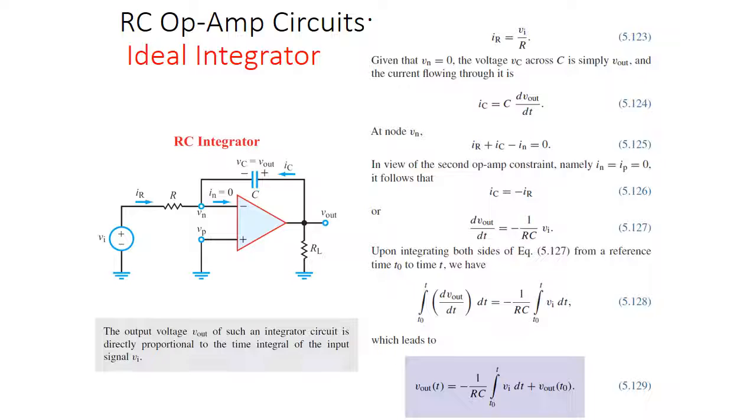We've got many examples of this coming up, but I do want to point out a couple of small things. Because op-amps produce the voltage out, that's the thing we look at with op-amps. We are able to produce that integration through the voltage of the op-amp coming from V out, and the feedback goes through that capacitor. As the circuit charges up, we're pressing less and less charge against those panels, so there's less current flowing through. That's where the feedback comes through. We're going to calculate a few of these in a minute.